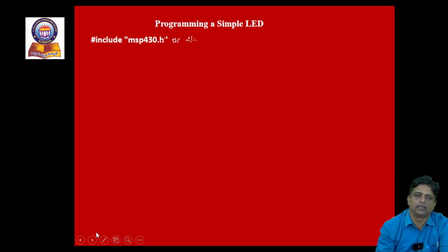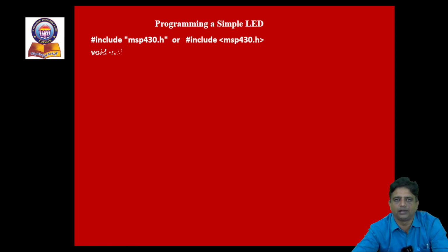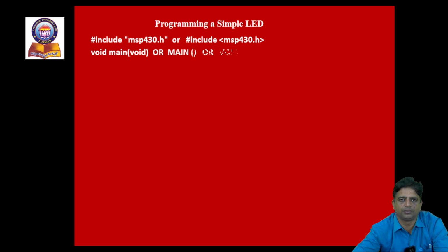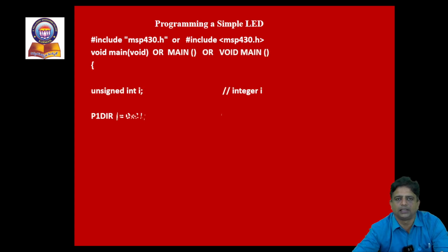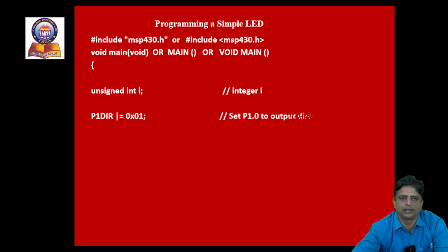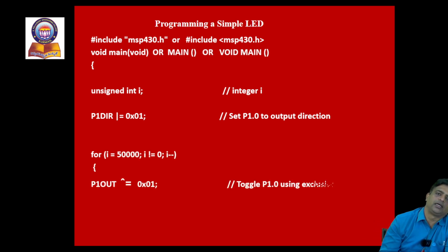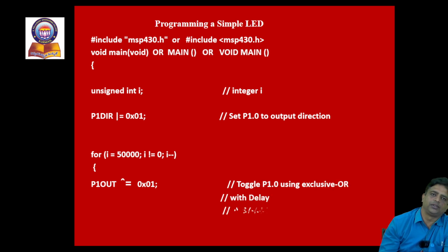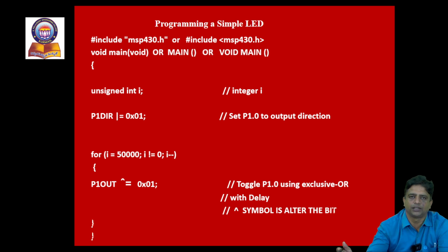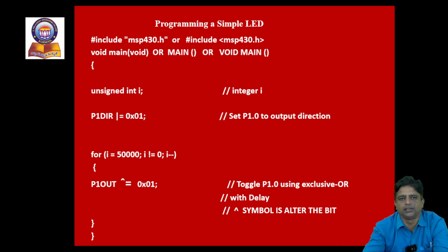So in general, whenever we frame a C program, we start with the introduction of libraries. Generally, we might have practiced stdio. These are the libraries with respect to MSP430. So whatever library we need to include, we are going to invoke that library. A simple representation of library invoking is as mentioned: hash include, either in angle brackets or in double quotes, MSP430.h.